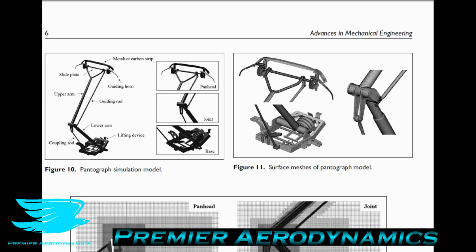So they said the temporal resolution in the simulation based on the finest voxel resolution was 9.18 times 10 to the minus 6. So this is important because the temporal resolution is linked to the voxel size, where the smaller the voxel size you have, the smaller the temporal resolution has to be. And this is kind of akin to the Courant number in Navier-Stokes CFD. The finer the mesh you have, the lower the time step you need to have, because if you have too high a time step, then effectively particles are traveling through too many cells between time steps. So you then start not being able to model the flow properly. So that's why you need to have a low Courant number.